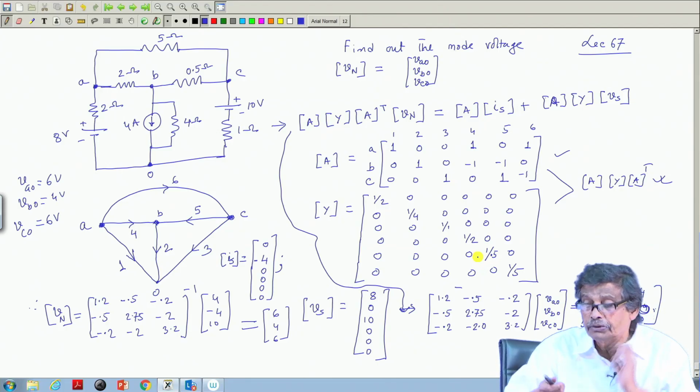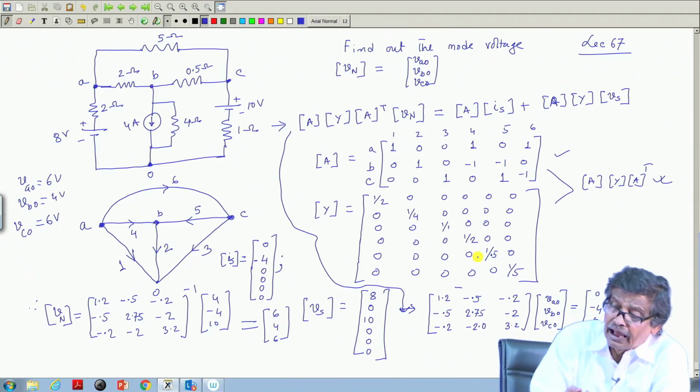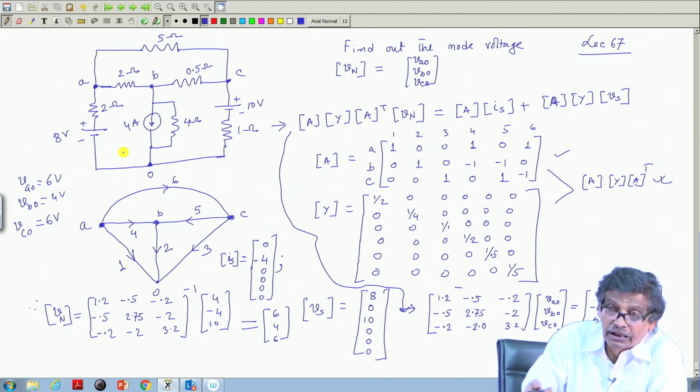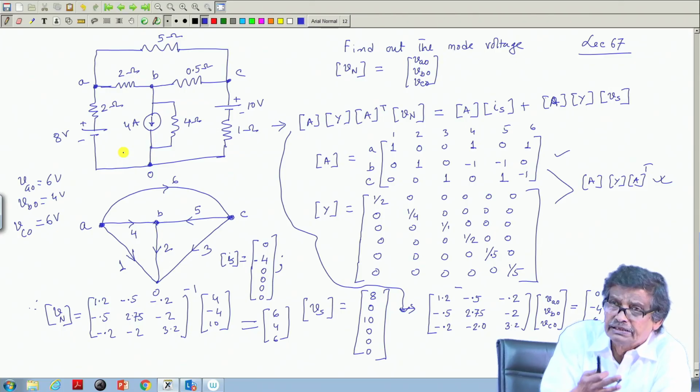Of course, you should not be under the impression that I could not also apply the fundamental loop method to do this. I leave it to you; for this network I have adopted the nodal method. If I ask you to find the fundamental loop currents, I think you will be able to do it: draw a tree, then draw the rest, and so on, as explained in the first example.